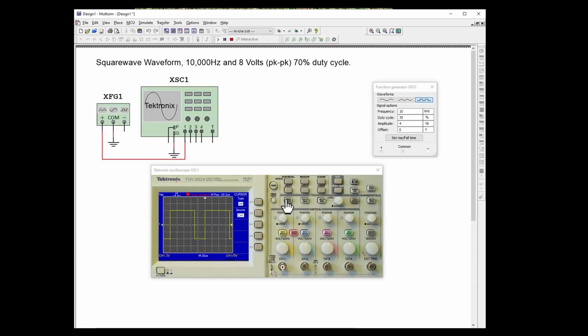So let's go ahead and go to time. So you got source, channel 1, voltage, time. So we're going to do time, and you see these 2 green lights come on? That means that they're active. So let's go ahead and we're going to measure the period. It's 100. So let's go over and measure the, there we go. So we have cursor 1 at minus 100, cursor 2 at minus 30, and the delta is 70, and that's what we want.